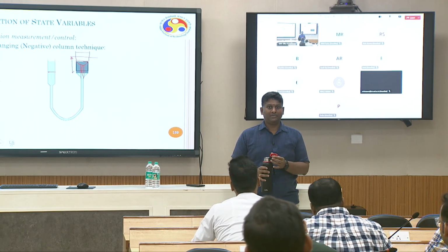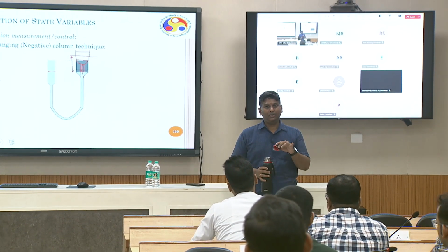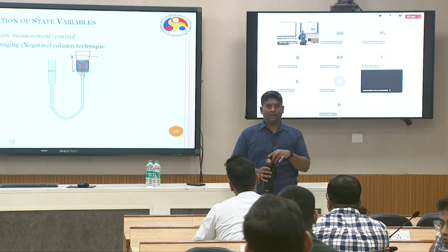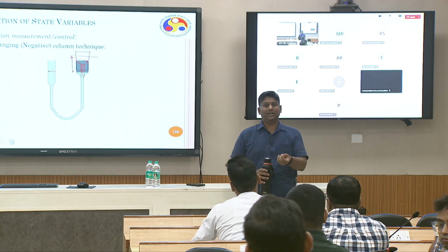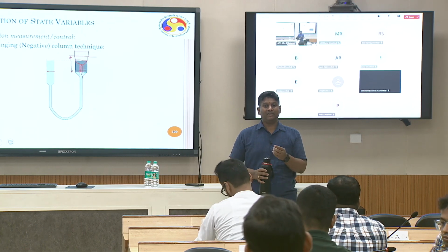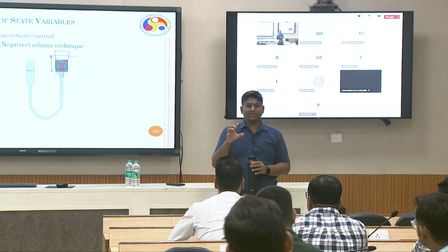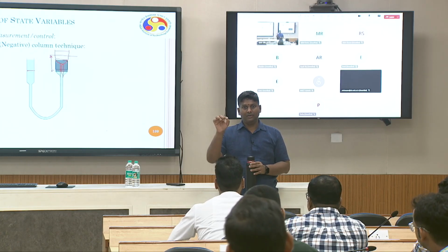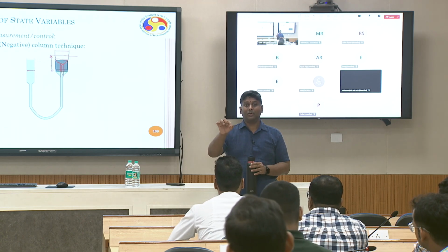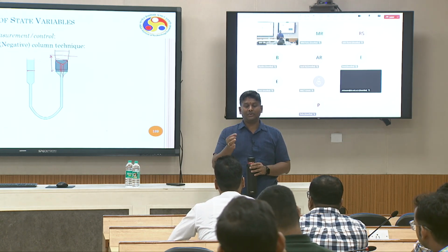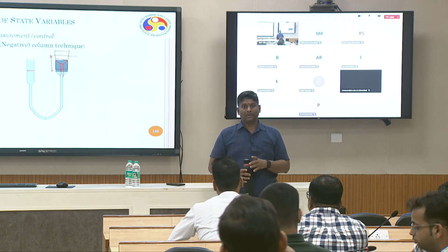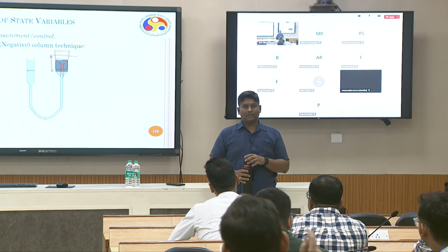If you are drying a soil mass, air should enter your soil system or pore system. At what point it is able to enter is described by the air entry, where exactly the desaturation starts. We have water entry and air entry, different points. In our drying system, we call it air entry. If your system is fully saturated and you are drying the soil sample, the point where air enters the largest pore of the system is called the air entry value. And water will enter the smallest pore if we are wetting.